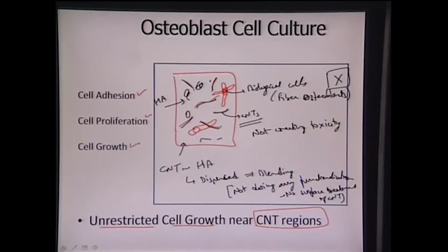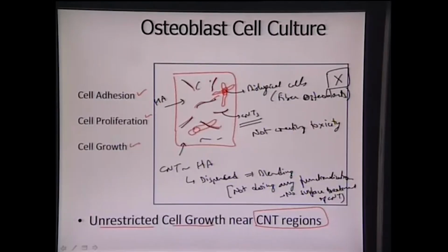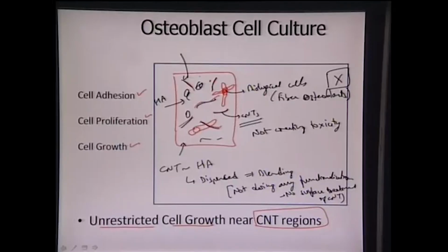That is the reason it appears that they have some sort of a chemical affinity with the hydroxyapatite surface, and that is why they are distributed so uniformly even after plasma spraying, and are able to enhance the fracture toughness by approximately 2 times. And to come back to the biocompatibility part, we are able to see that all these osteoblasts are growing on the hydroxyapatite surface, which even has CNT, without any hindrance. So it means that the overall composite is not toxic. Therefore, this overall material is showing superior mechanical properties while rendering a biocompatible nature to the implant surface. So this material can serve as a superior coating, imparting a superior biological response while maintaining much better mechanical properties.